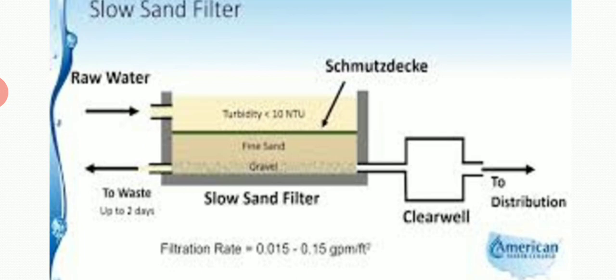So when the impure water is trickling down, if it has any colloidal impurity, that colloidal impurity settles down in these voids. This process of colloidal impurity settling in tube settlers is known as sedimentation. So this is the second process. One is mechanical straining and the other one is sedimentation.